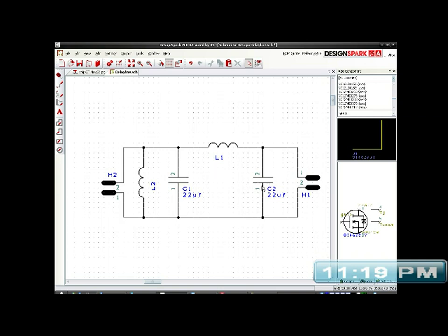So what I'm saying is, if we can store energy in this capacitor here, it'll be delivered a little bit slower through L1 to C1 and L2, which is our exit coil. So we end up with a pulse from this capacitor here, but we want to sustain that pulse as long as possible. And so what we do is have an adjustable tap on this coil.